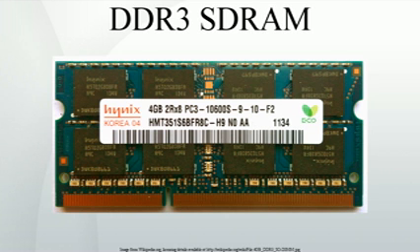Introduction of asynchronous reset pin, support of system-level flight time compensation, on-DIMM mirror-friendly DRAM pinout, introduction of CWL (CAS write latency) per clock bin, on-DIO calibration engine, read and write calibration, fly-by command/address control bus with on-DIMM termination, high-precision calibration resistors.